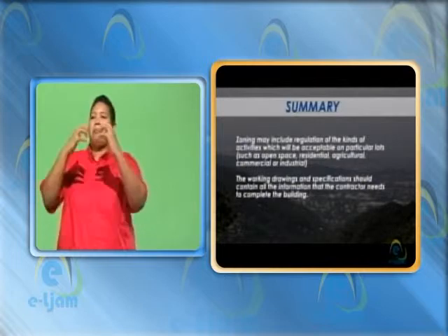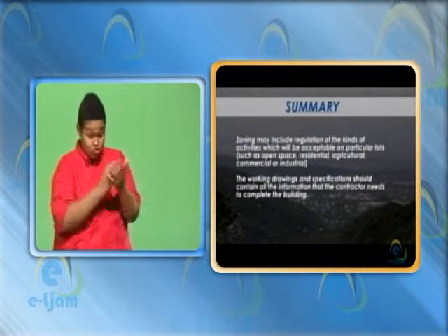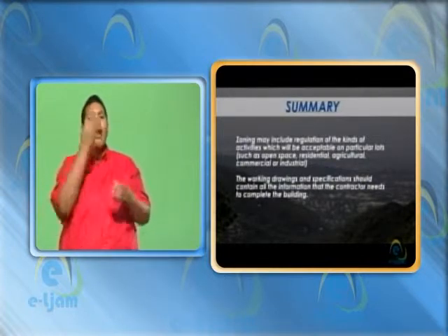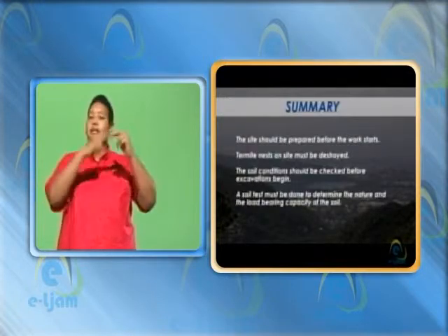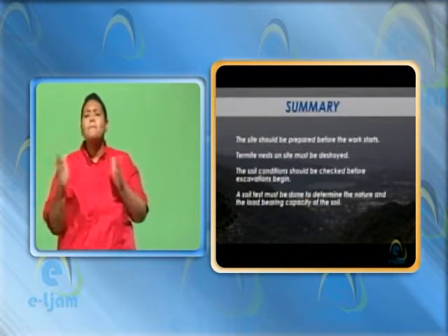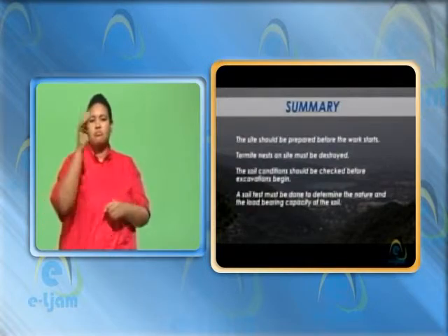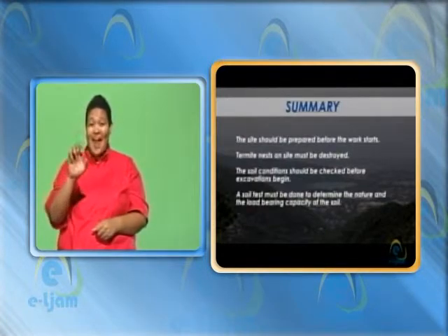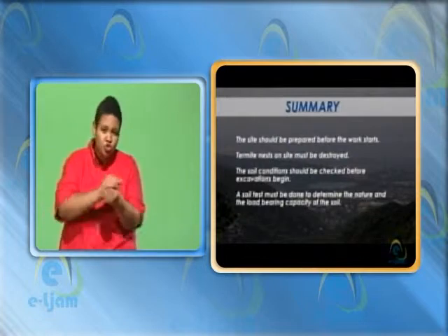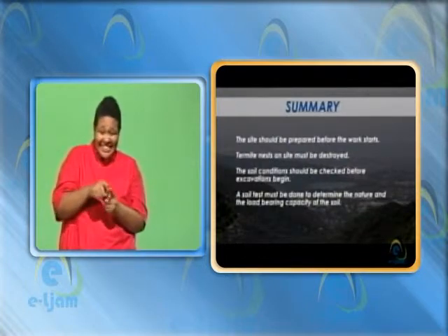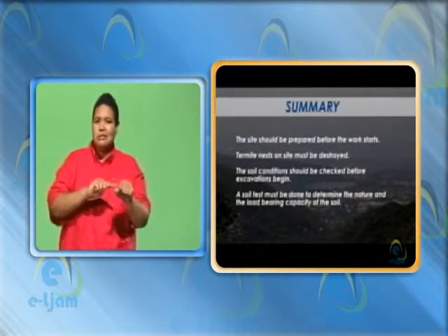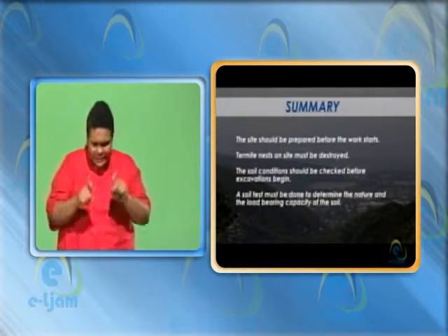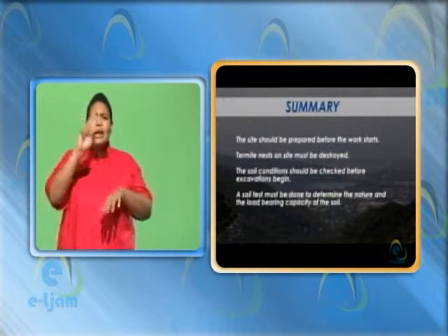The working drawings and specifications should contain all the information that the contractor needs to complete the building. The site should be prepared before the work starts. Termite nests on site must be destroyed. The soil conditions should be checked before excavation begins. A soil test must be done to determine the nature and load-bearing capacity of the soil.